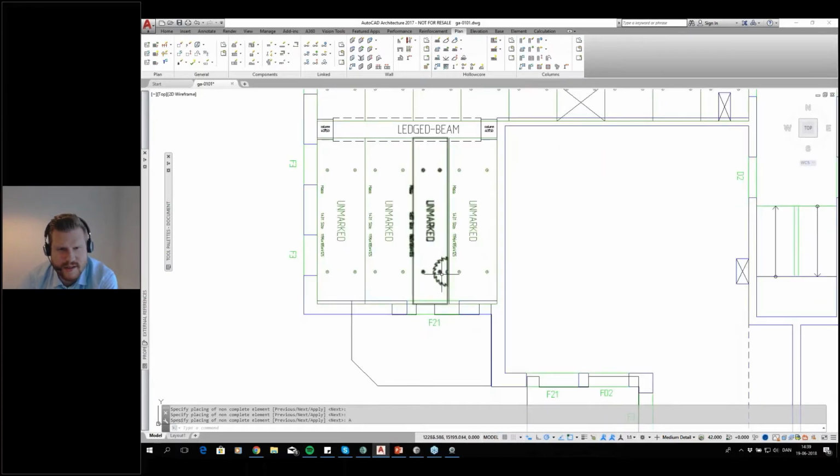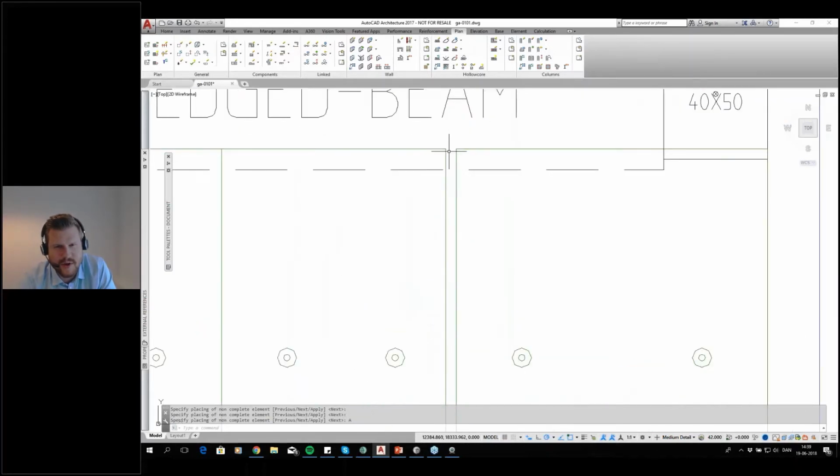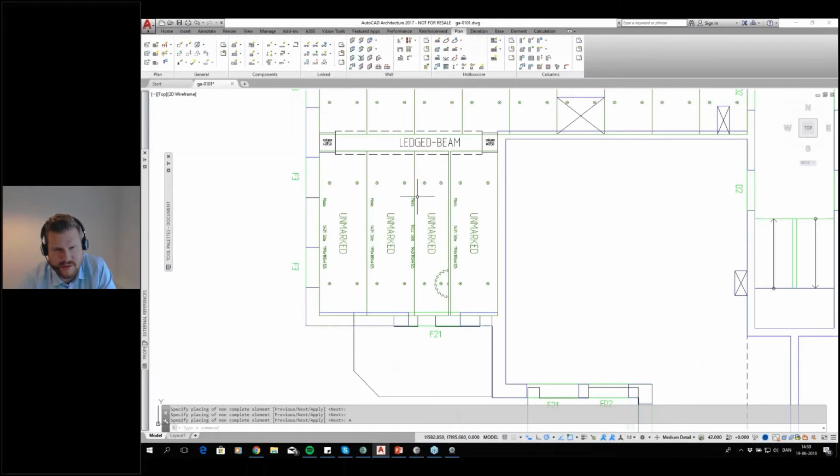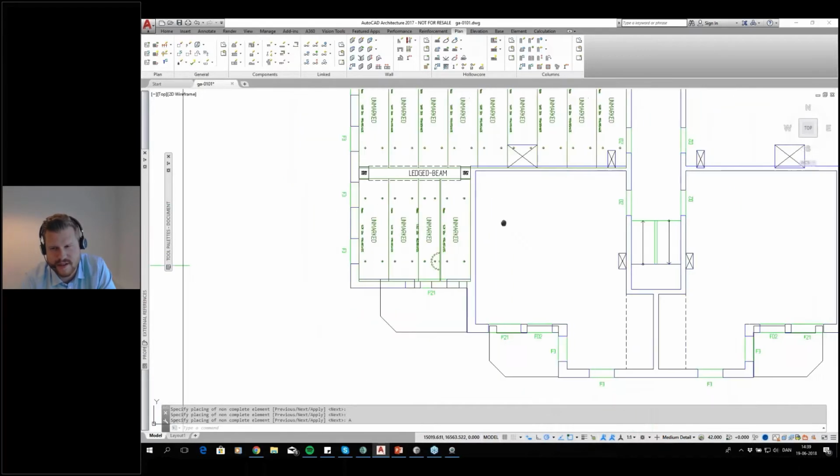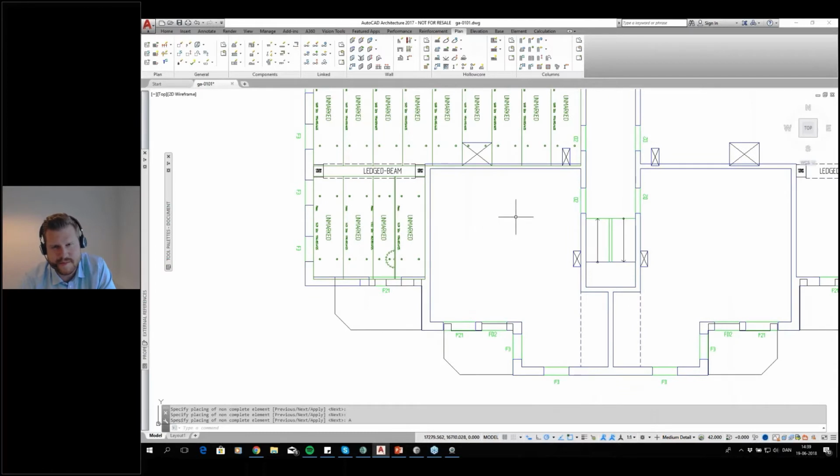And what I'll get here is a saw. And of course, that suggests where the hollowcore should be cut. And as you can see, the lifters here are also placed accordingly. And we can even see here that we have a small gap. This is because the cutting rules allowed for where I can cut my hollowcore, allow for different increments of cutting. And we'll also look at that in the definition just in a few minutes.